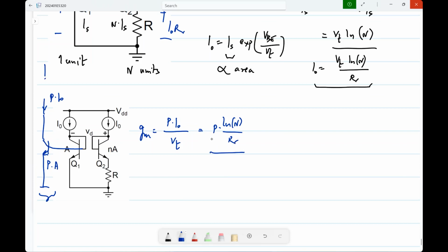So we went from constant voltage biasing for MOS transistors to constant current biasing because the GM would be less sensitive to transistor parameters and temperature, right? Now in bipolar transistors, constant voltage biasing is impossible anyway. You always use constant current biasing. But in both cases, there is still some dependence on temperature.